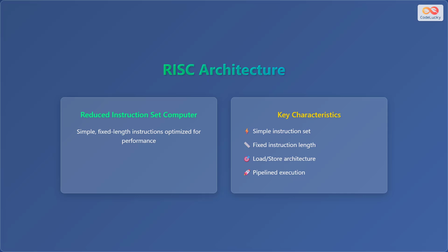It follows a load or store architecture, where data processing instructions operate only on registers and data must be explicitly loaded from memory into registers before being processed and stored back into memory afterward. Finally, it supports pipelined execution, which allows multiple instructions to be processed concurrently in different stages, improving overall performance.